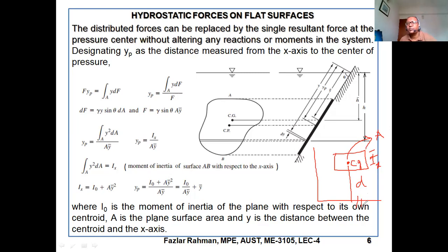Which formula will apply? Parallel axis theorem. You remember in engineering mechanics that the inertia of an object about the x-axis equals the inertia of the same object along the x-axis with respect to the CG of the body plus area into d square, A d square. This is called the parallel axis theorem.